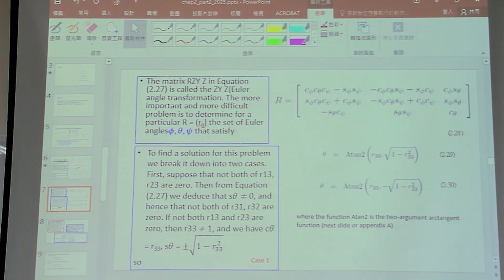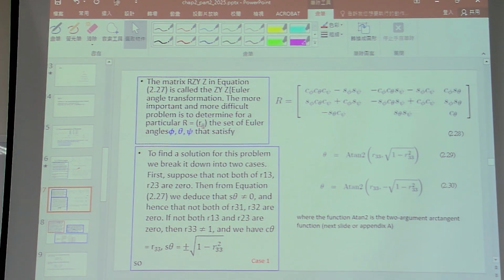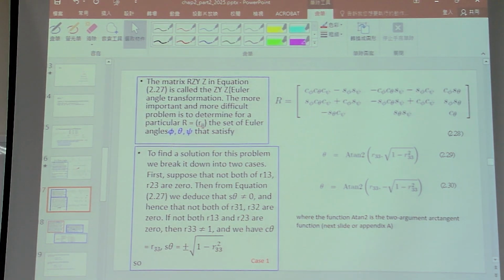There's another need. We need to do the inverse calculation, because if we have the angles, it will be fine. But if the user just provides you the R matrix, with the element quantities already on it, how can you refer back to the 3 angles? Let me rephrase.